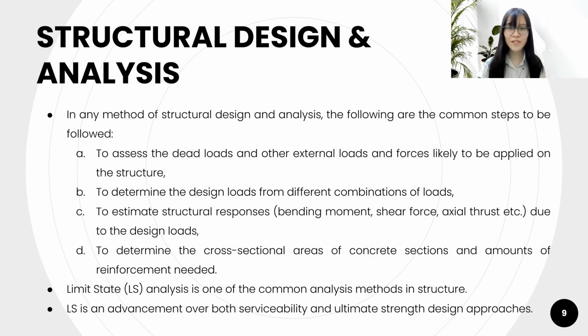Now, let us look into the structural design and analysis of our case study. In any method of structural design and analysis, there are some common steps that need to be followed. First, you have to assess the dead loads and other external loads that are applied to the structures. Second, you have to determine the design loads from different combinations of loads. Third, you have to estimate the structural responses, for example, bending moment, shear force, axial thrust, etc. due to the design loads.